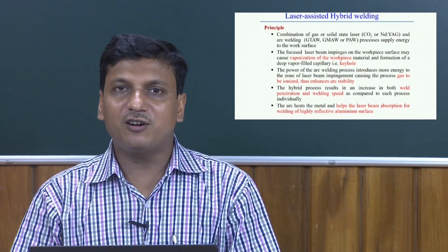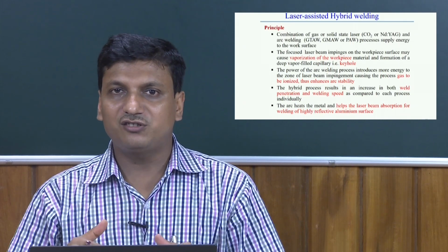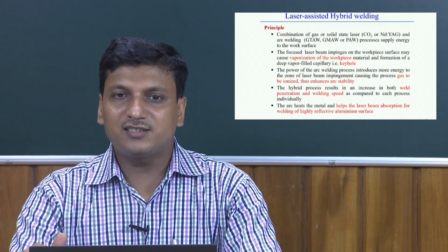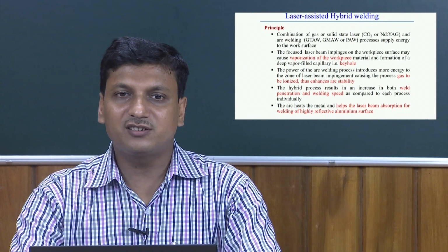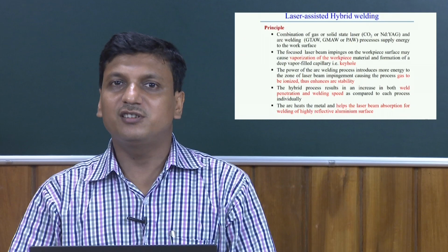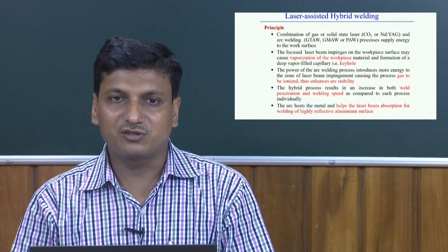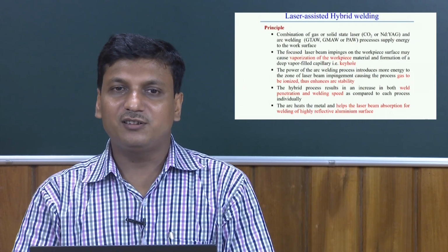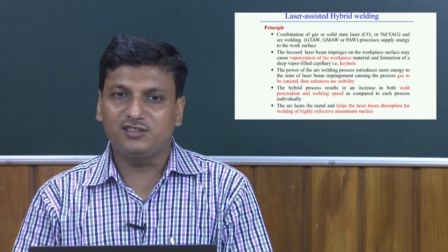Now, the arc in the arc welding process introduces more energy, and the laser helps the gas to be ionized, and in that sense the laser enhances the arc stability in the hybrid welding process. So the laser helps in the formation of the arc and its stability.